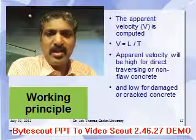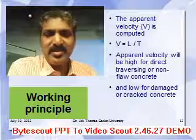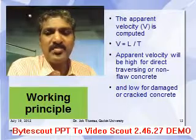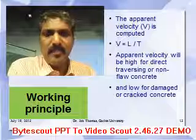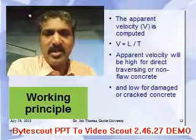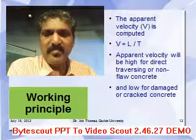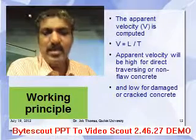So in this approach, we calculate the apparent velocity: the velocity is equal to the length between the receiver and the transmitter divided by the time taken for the traverse. The apparent velocity will be high for direct traversing and non-flaw concrete, and the apparent velocity will be low for damaged concrete or cracked concrete.